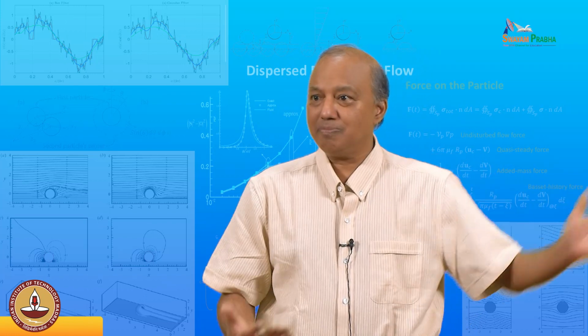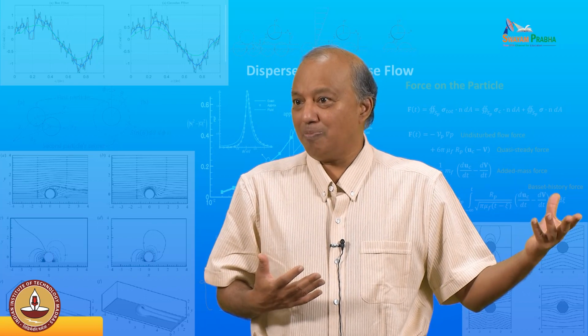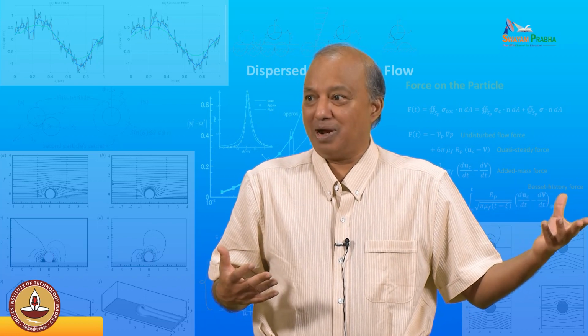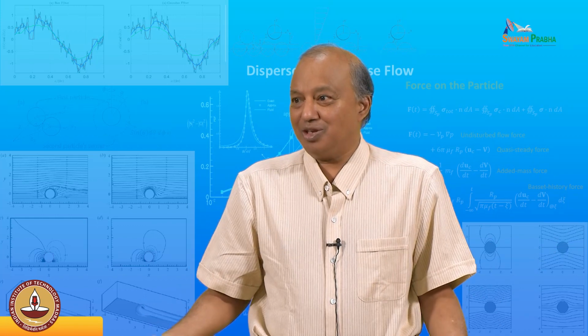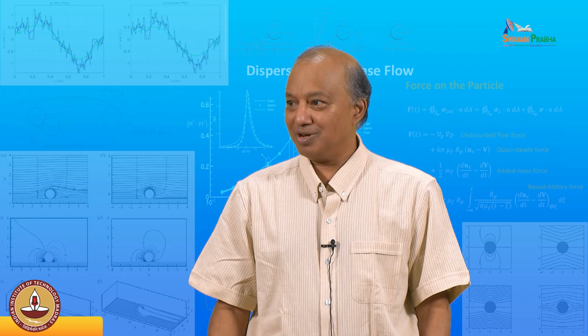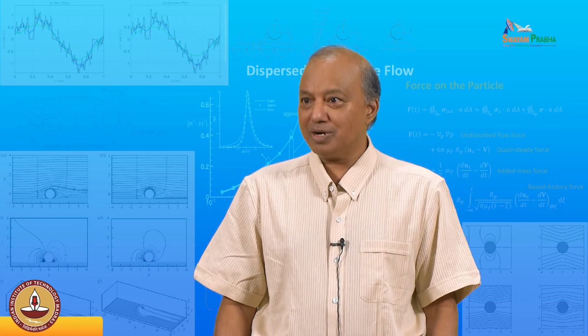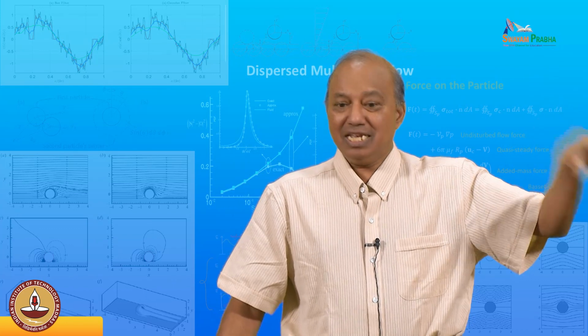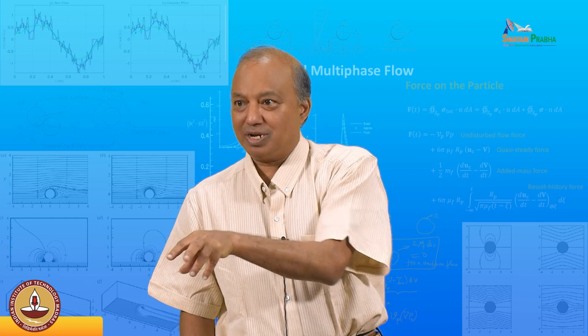You compare them. And if the back coupling is 10 to the power minus 3 or 10 to the power minus 4 smaller than the others, then the code itself is telling you it's not two-way coupled. It's not that big a deal. So two-way coupling is important only if that added force is comparable to everything else in your Navier-Stokes equation.